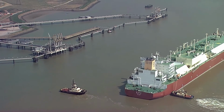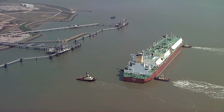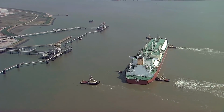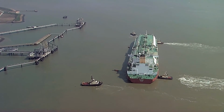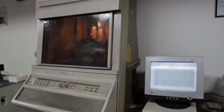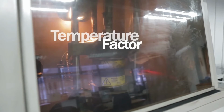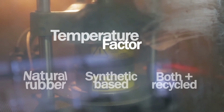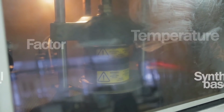Temperature factor is vital in determining the impact of low and high temperatures on the energy absorption and reaction force of the fender. It plays an important role in both the design of berthing structures and the selection of fender systems. Like velocity factor, temperature factor is highly sensitive to the type of rubber used: natural, synthetic, a blend of the two, or recycled. This will vary from manufacturer to manufacturer.